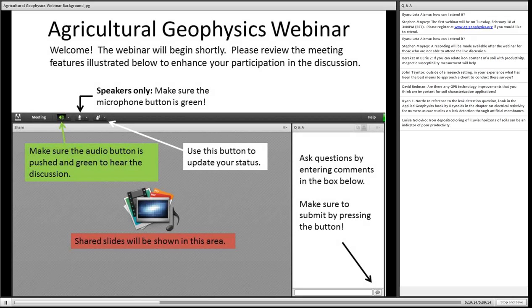Although, once again, your success at this is going to be limited to areas, perhaps wetlands, with inherently low conductivity. But if you had, say, salinity in this mix, the conductivity from the salinity would mask the more subtle in-phase effect of susceptibility. Yeah, that's what I can think of offhand.